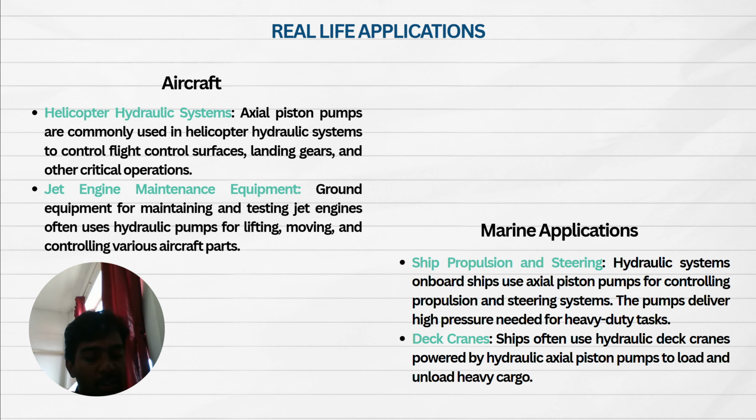And for the last application, it is marine, where we can see that hydraulic systems on board ships use axial piston pumps for controlling propulsion and steering systems. The pumps deliver the high pressure needed for heavy duty tasks. And we can see here that ships also often use hydraulic deck cranes powered by axial piston pumps to load and unload heavy cargo.